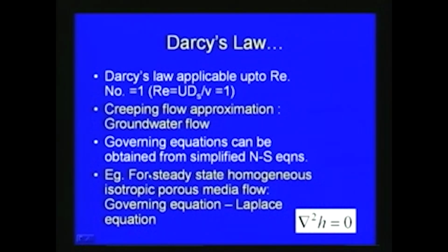Through the simplification of the Navier-Stokes equation, for example, if you consider steady state flow in homogeneous isotropic porous media, the governing equation is the Laplace equation, del square H is equal to 0, where H is the head or the water table height for the problem considered. Like this we can also start from the Navier-Stokes equation and then try to get solutions.